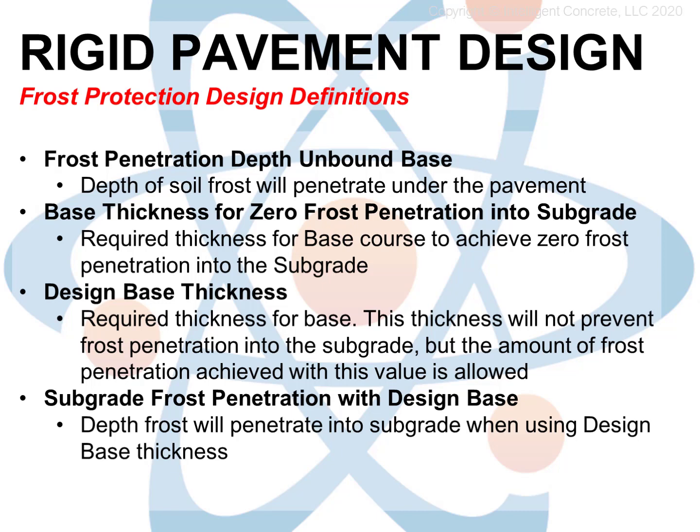Subgrade frost penetration with design base is what it sounds like too. It's how much farther into the subgrade frost will penetrate below the prepared layers of base and subbase. If we keep this to a fairly short distance, say less than a foot, then there's just not a lot of frost heave that can occur.